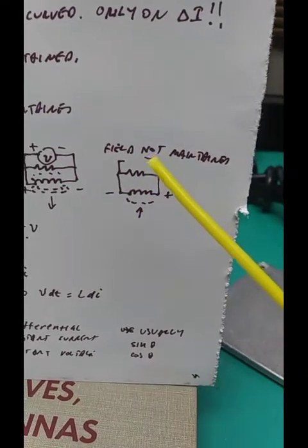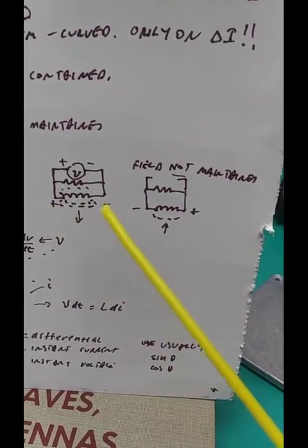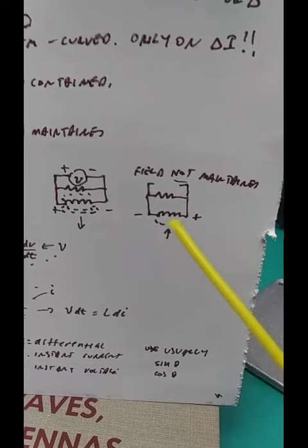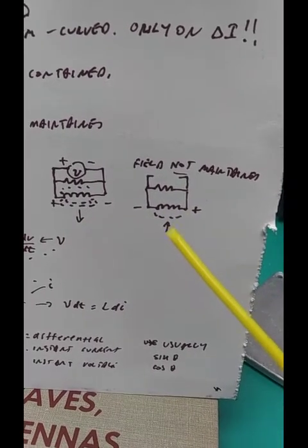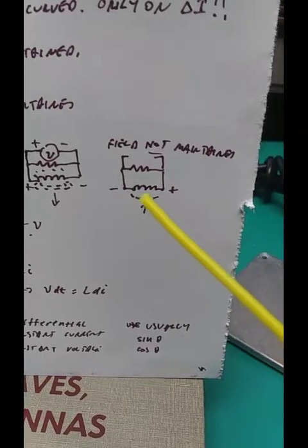When the potential source is taken away, the inductor, which was formerly positive on the left, negative on the right, flips polarity as that field discharges the opposite direction. Opposite field direction, opposite direction of current flow. And a resistor is shown there to give that current a path to go through.